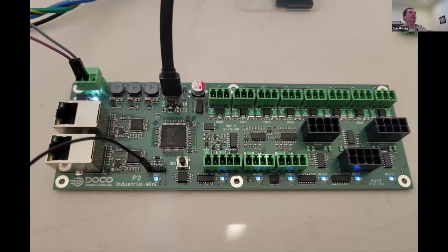So anyway, we put a USB-C connector on this thing. That was kind of fun. And a little FTDI chip behind the connector. And here's the flash. We put a serial port on it for the next gen displays. There's 2 Ethernet ports. There's a 5, a 3.3, and a 1.8 volt switching power supply.